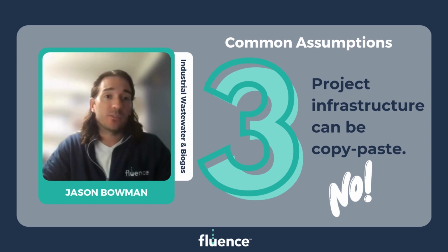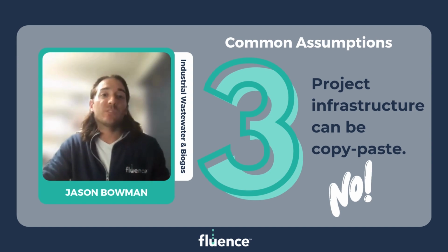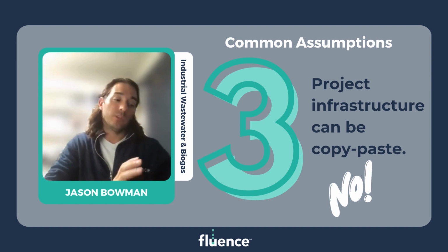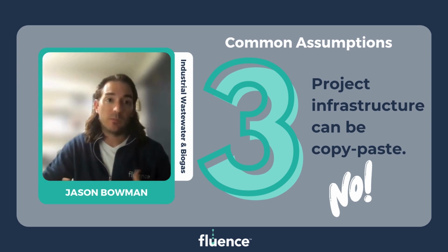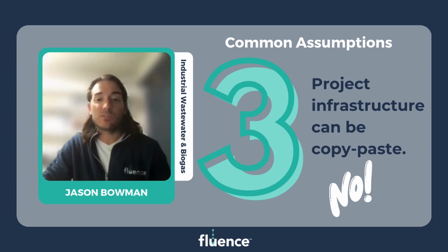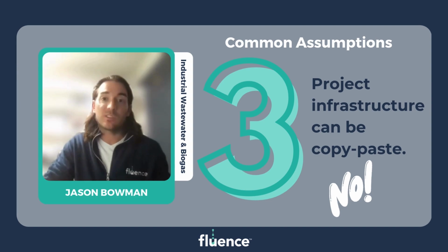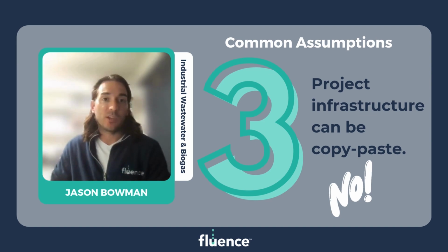Whether it's the environmental standards or the regulatory landscape, treatment goals, literally the physical site conditions, there are always differences that require some modification from an existing project to a future project if you're trying to utilize the same treatment scheme. So don't get me wrong, we routinely use past projects to estimate future projects, but 9 out of 10 times there's going to be a difference in the tank or a difference in the dewatering mechanism, a difference in the hydraulic retention time, a difference in how much ammonia needs to be removed, phosphorus, etc. So a lot of different reasons why you cannot always copy from one project and directly duplicate in another project.